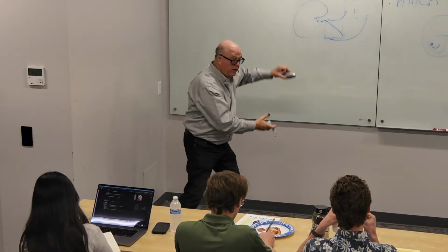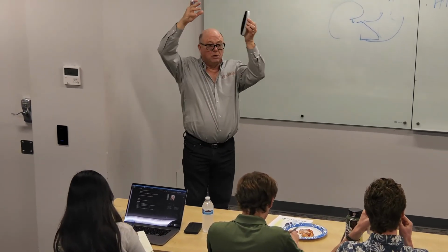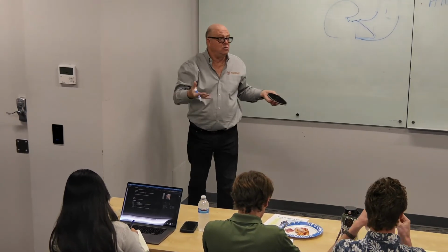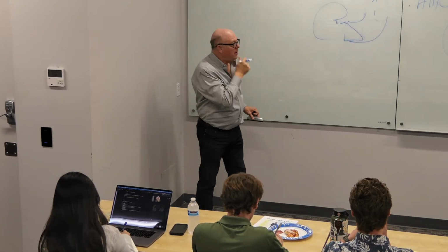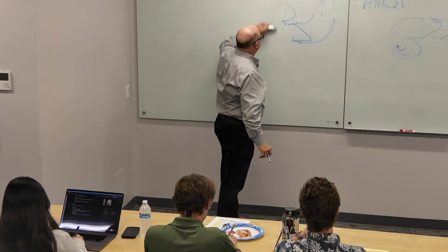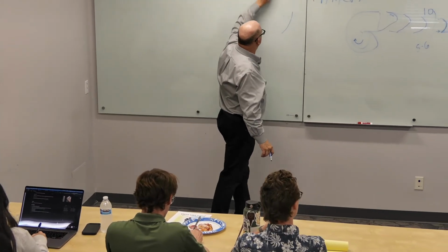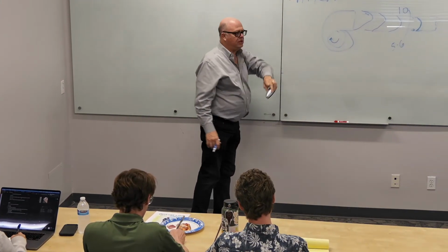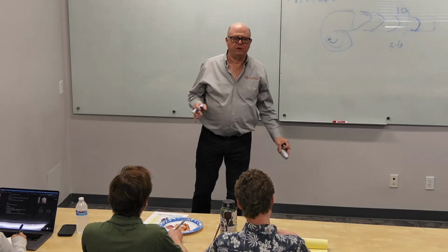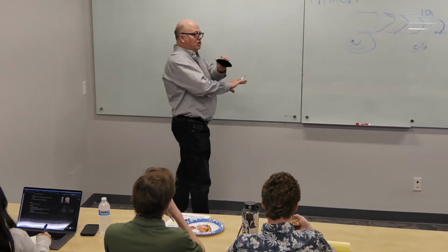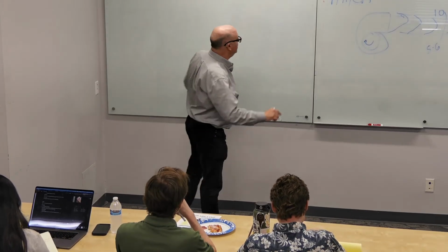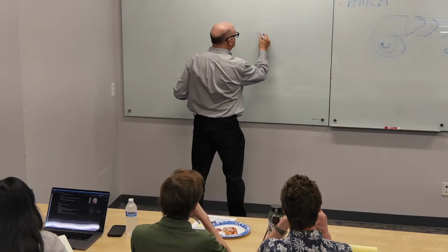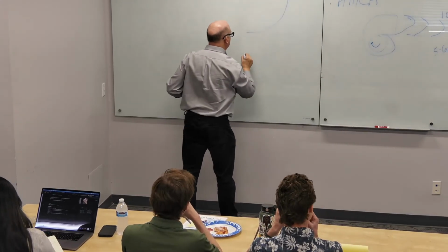And the longer radius you make it, the more gradual it is, and so the less losses you would have, right? As opposed to a short radius. I was always taught, and I think there was at least one surprise for me on Mike's sheet, but what I was always taught is that the least system effect elbow is a long radius, which makes sense, right?